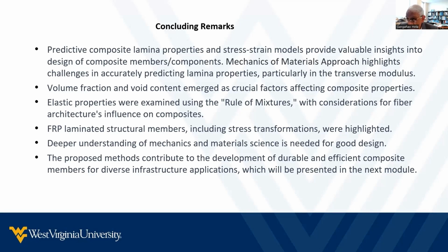Elastic properties are examined using the rules of mixture with consideration of fiber architecture's influence on the composite. And that fiber architecture influence is transformed into a global axis utilizing what I have shown as the stress transformation matrix. And certainly, a deeper understanding of the mechanics of materials and material sciences approaches are needed. The proposed method contributes to the development of durable, versatile composite materials for diverse infrastructure applications.